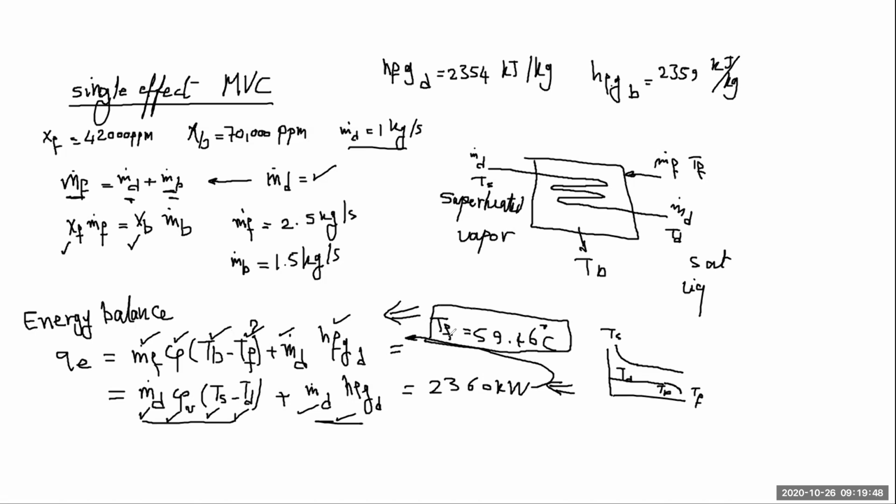One question regarding that. Regarding the compressor here, inlet and outlet, the temperature at the outlet of the compressor is at TS, right? Yes, exactly. This is the condition which leaves the compressor. And the condition at the inlet of the compressor is this: we have m dot distillate at a temperature T vapor.